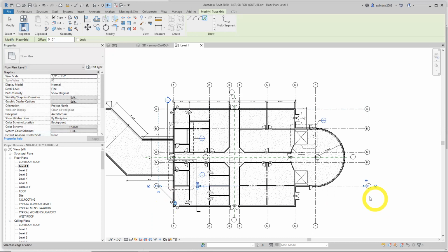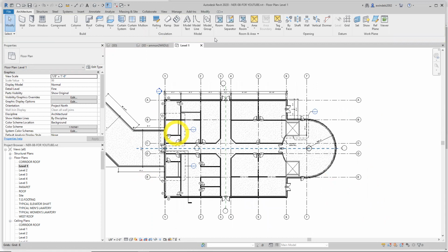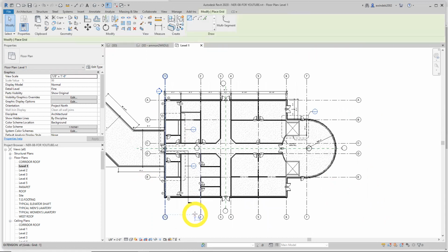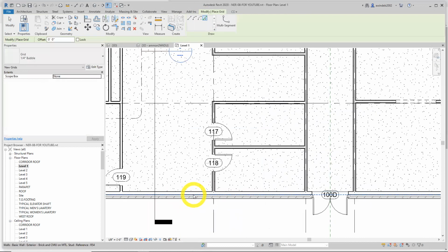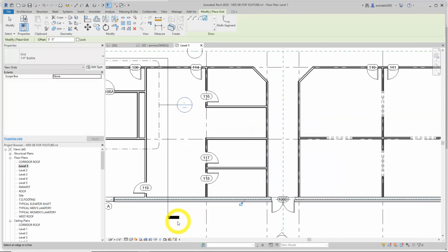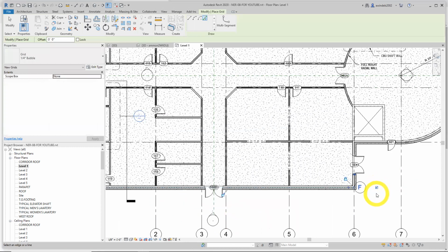There they go, though. This one actually looks good, too. It'll queue up this one, and then it aligns with the rest. Let's make our last one. Good. Pick line, exterior wall, center of wall. Let's turn on both sides if they're not already. They usually shouldn't be.